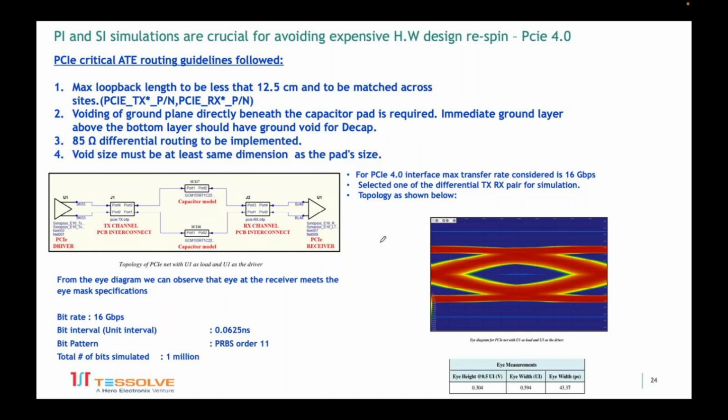So whatever capacitor, vias or MEMS parts you put in, get those model files and build them in and simulate properly, just to make sure that at the simulation level it is taken care of. And when we fab, you need to really look at a fab which has tighter tolerance in terms of manufacturing, so that what you simulated will go close to the real performance.